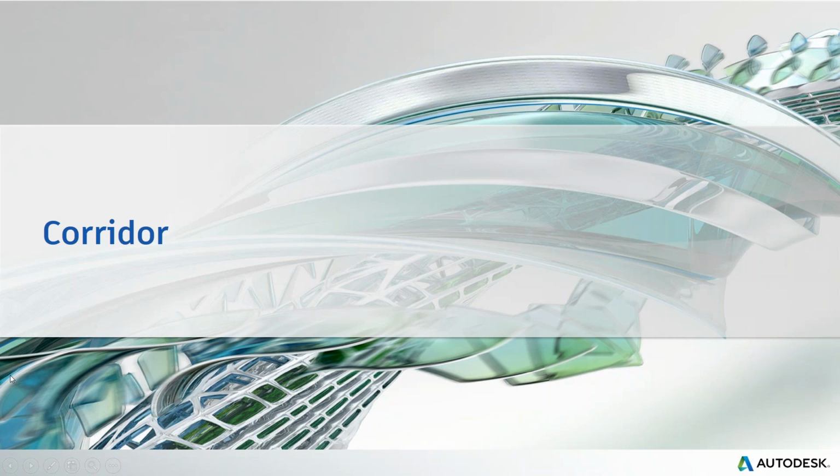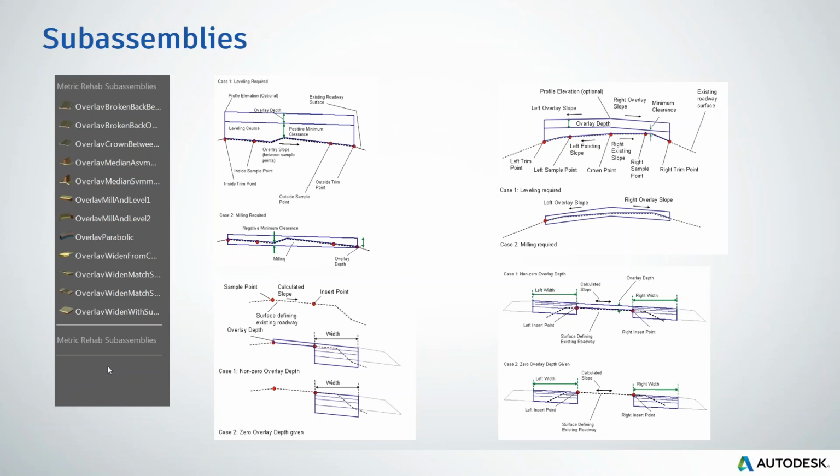So next is to build a corridor. So we have alignment and profile, we have existing conditions, which means triangulation. So let's have a look at what we can do with the corridor. Before we build a corridor, what we need is subassemblies. And there are, you see, rehab subassemblies.